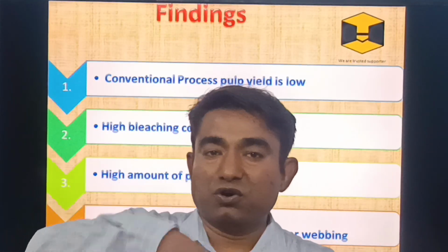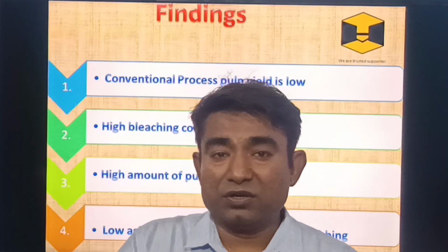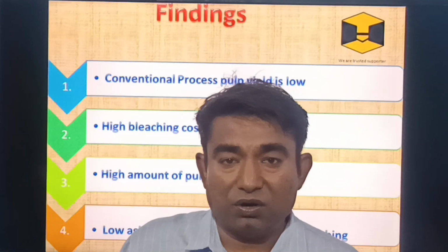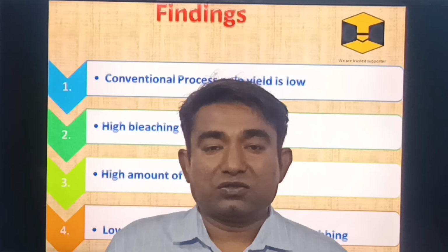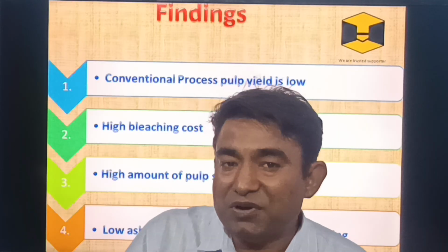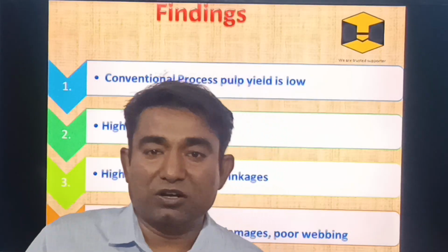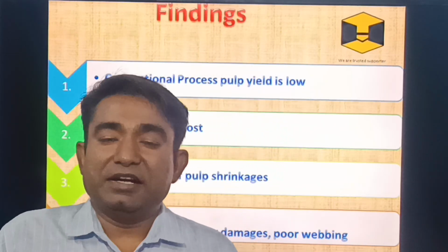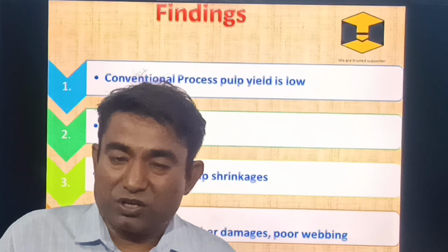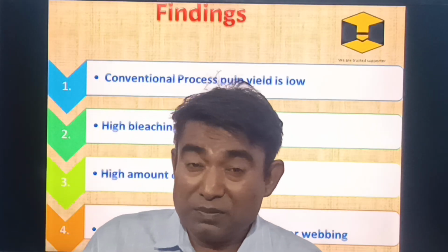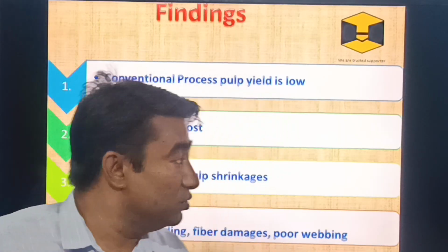If hemicellulose has been degraded or dissolved in the liquor, the fiber won't have much strength. So we desire both cellulose plus hemicellulose. Industry wants a selective cooking process which could preserve the cellulose and hemicellulose.